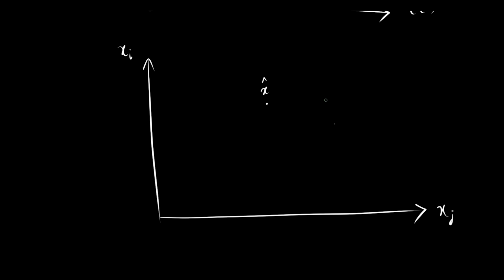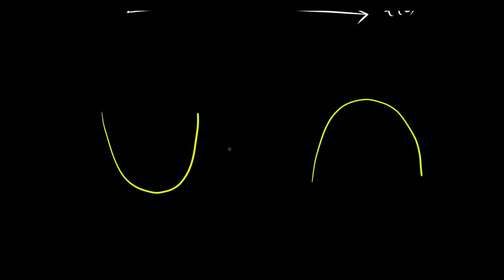Just because a system is at an equilibrium point doesn't mean it's stable. The state variables may not be changing, but when disturbed, the system might still become unstable. Here's a simple analogy. Imagine a ball resting on a hill. In one case, the ball is nestled at the bottom of the hill. In another, it's perfectly balanced at the top. In both cases, the ball isn't moving. So, both are equilibrium points.